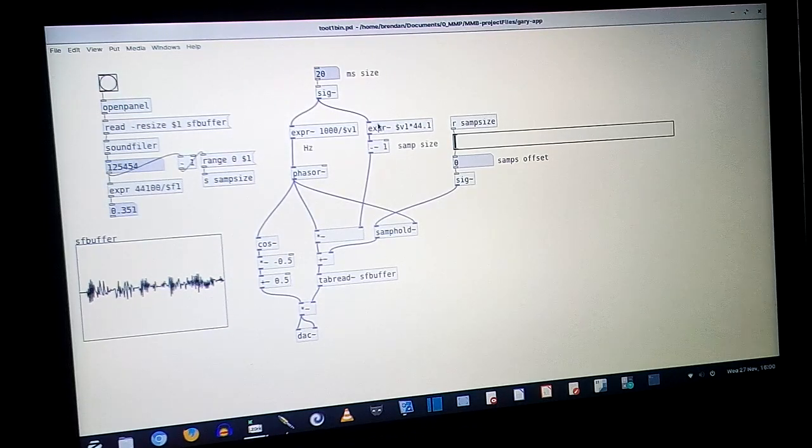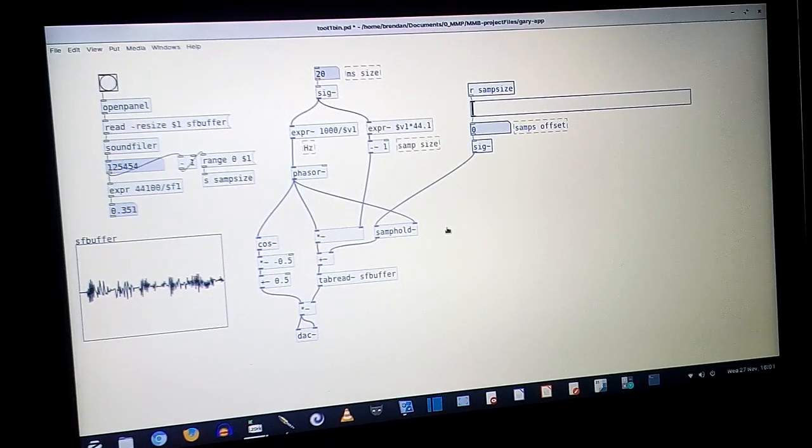And one way to ameliorate these amplitude modulation artifacts is to create a copy of the part that's doing the reading, the window, and overlap it 180 degrees out of phase, or offset by 50%.